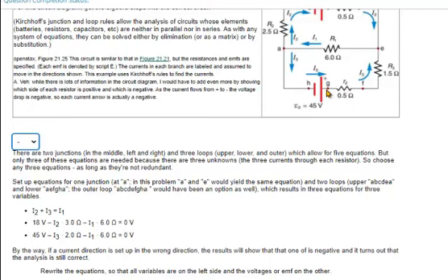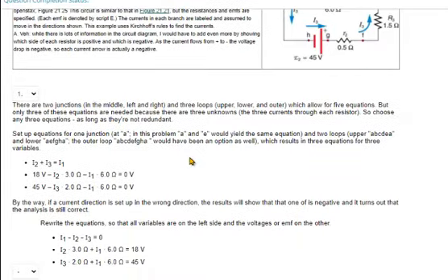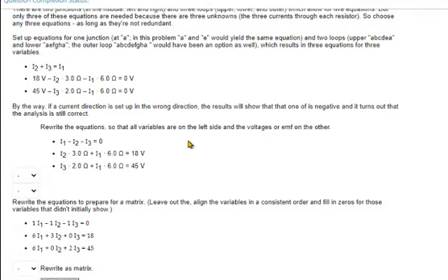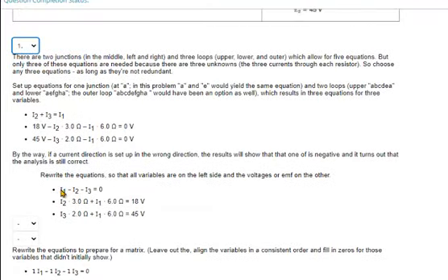Then here we can see nicely, yeah, 3 ohms here, and I have a voltage drop, so 3 times I3, there it is. And then I'm going to go through here, again a voltage drop, the way it's drawn, and I have 6 ohms times I1, and then I return here, and I'm back to 0 voltage, which I wrote here and here. So these are the 3 simultaneous equations.